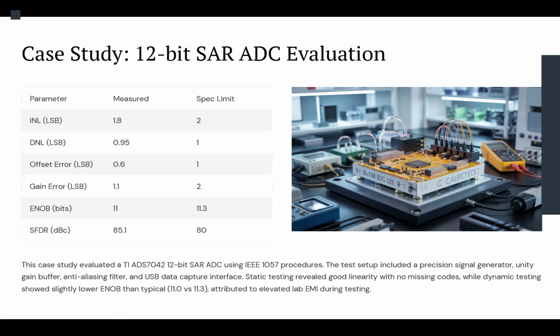The definition of stabilized temperature is when the temperature varies or increases less than 1 degree Celsius in 1 hour. If we have such a slow temperature rise, then we can say that the temperature is stabilized.